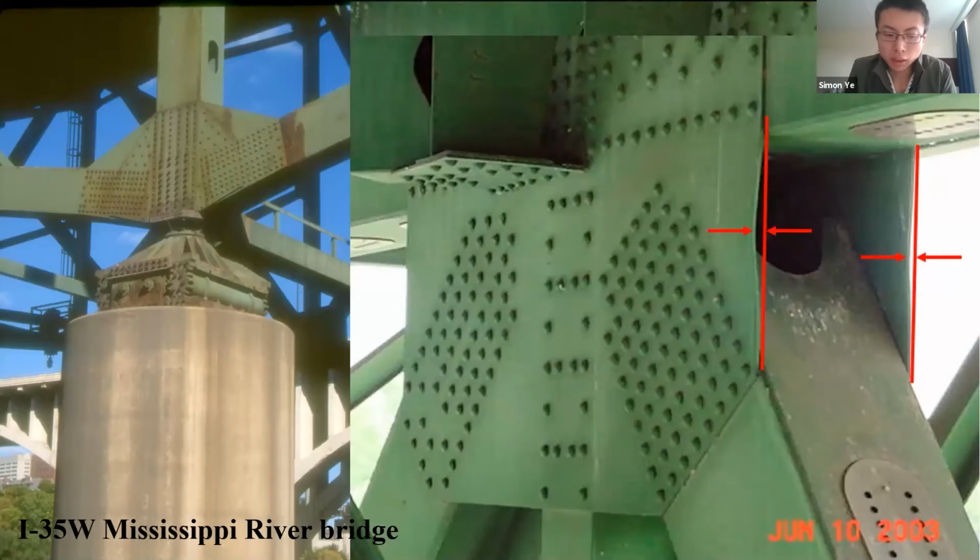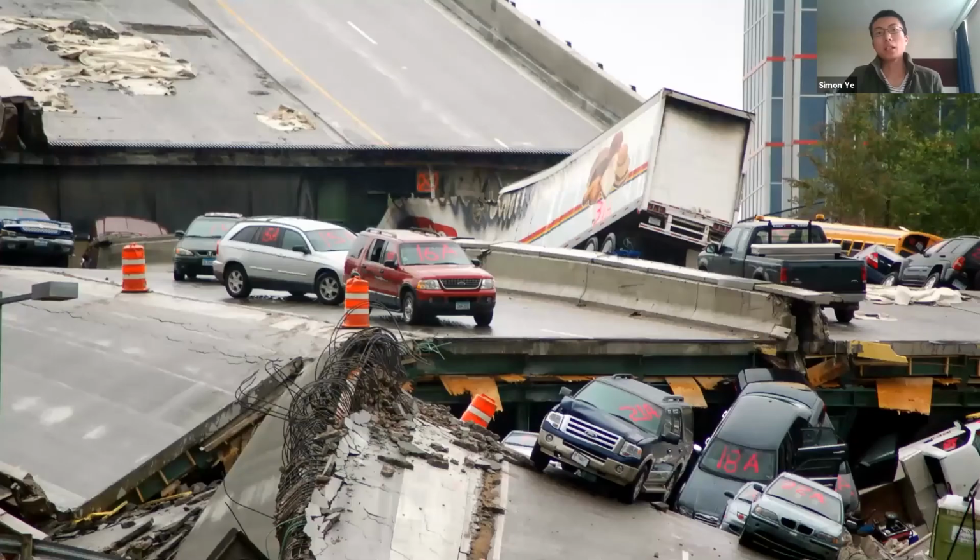If you look in detail, there is a slight buckling of the plate, indicating that the plate is overstressed and probably too thin. If the inspector or the engineer doesn't have enough engineering knowledge about the bridge behavior and performance, this problem will probably go unnoticed. And that can cause catastrophic consequences. This is the same bridge. The slight irony about this bridge collapse is that the bridge was inspected quite frequently and in detail because they already knew that it was a structurally deficient bridge, so they paid a lot of attention to it, but the bridge still collapsed.